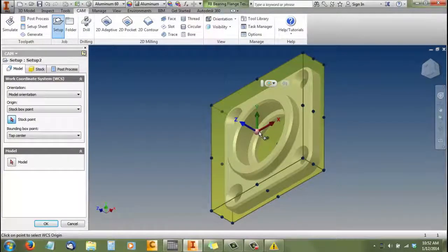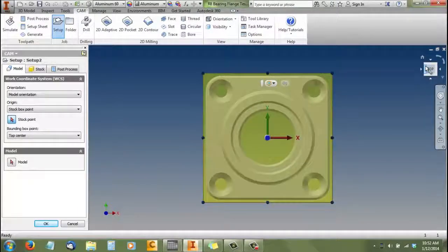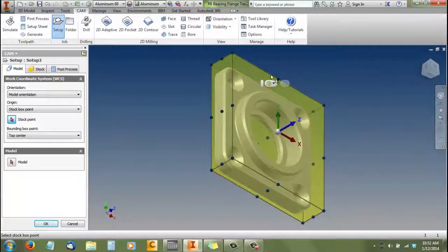This is G54 right now. This is the default position. So the first thing we want to do is change that default position. We'll define the coordinate system here in the software, and then we will tell the machine where the coordinate system is as well, and they both have to be the same. If they're different, you don't get what you want. With the CAM stuff, you start and you have these tabs, and you just work across these tabs, and your problems unfold in front of you and you solve them, and that's your workflow. So that's kind of nice.